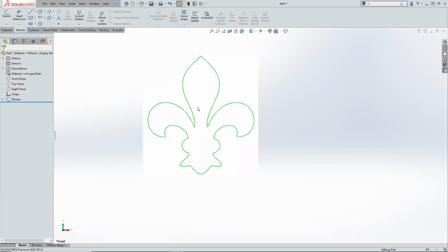Okay, so there's my picture. I'm going to trace it. So if this is your simple planar part, you've got the dimensions maybe between a couple of holes, or top to bottom. That dimension really wants to be something large, something overall, something critical perhaps. You know, again, it can be adjusted afterwards, but overall is good, so you get a good reference to the overall dimension.